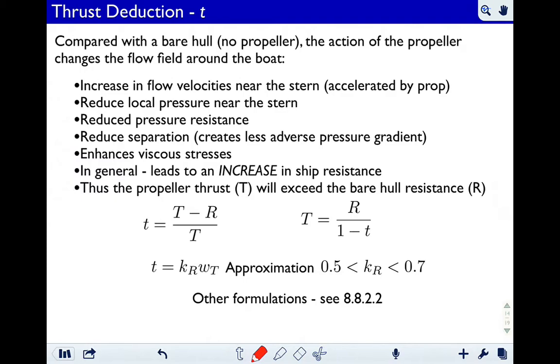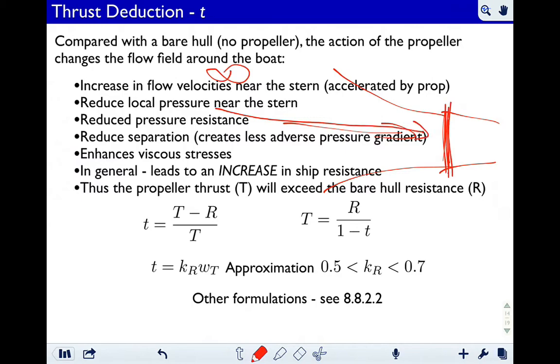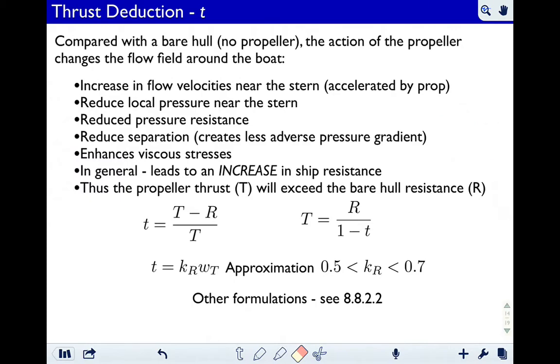As we mentioned when we first talked about propellers, if you have a propeller disc here for momentum theory, it pulls the flow in, right? So you have these converging streamlines. The flow is moving this way. The action of this propeller is to cause a pressure jump and momentum jump across it. It's adding momentum to the flow. That's the job of the propeller. That's what the horsepower does. Compared to the free stream velocity out here, the flow is already accelerating as it hits the propeller disc and then accelerating even more on the backside across the disc. So the propeller itself modifies the flow in the stern of the ship, and it causes an array of things to happen just by putting it onto the boat.